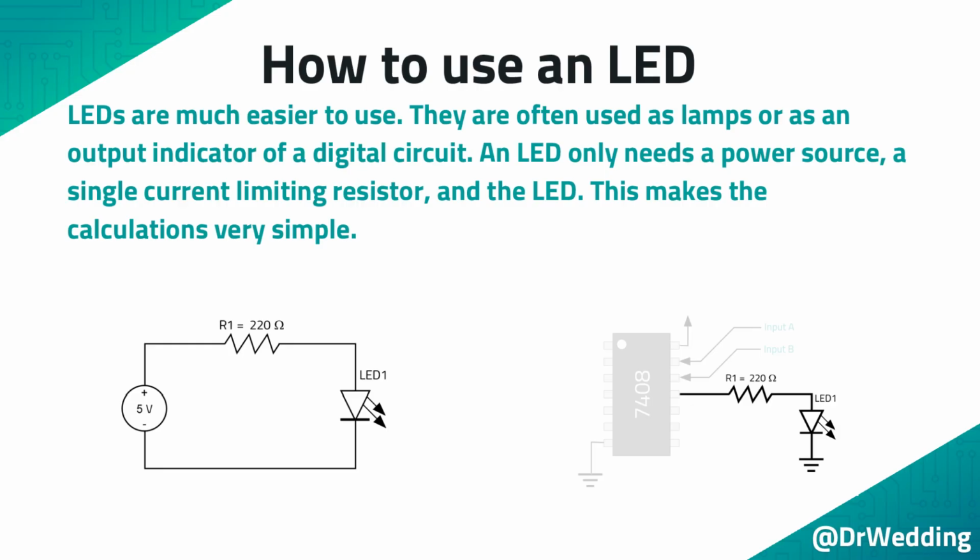LEDs are much easier to use. They are often used as lamps or as an output indicator of a digital circuit. An LED only needs a power source, a single current limiting resistor, and the LED. This makes the calculations very simple.